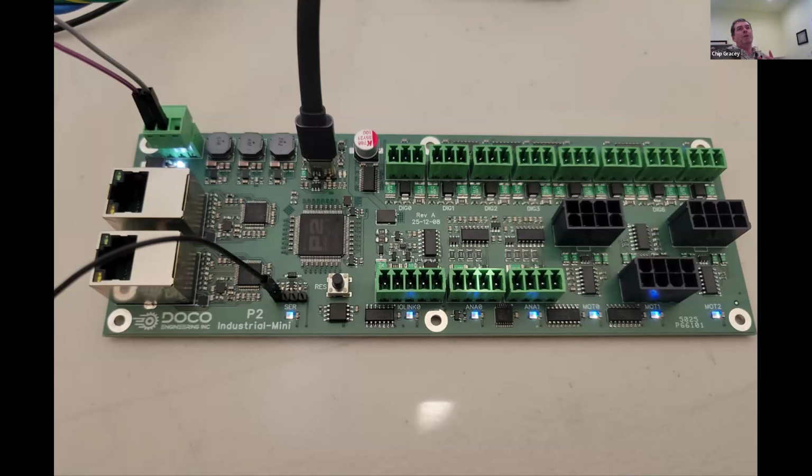And you do that for 2 bit periods, so 600 nanoseconds. And then at the end, you have 300 nanoseconds of low. So there are 4 equal bit periods, but only 3 states, right? Because you've got the initial high, you've got your data bit, which is held for 2 bit periods, and then you've got the clear at the end, a bit that has to go low so it can register the next high. So you have 3 bit states for each bit that gets shifted out.